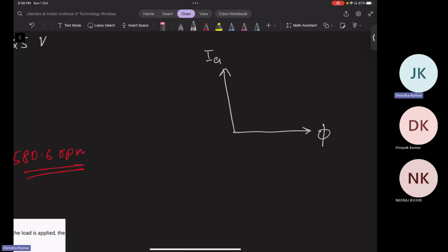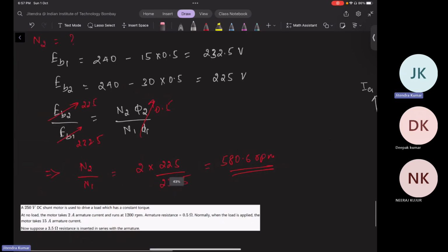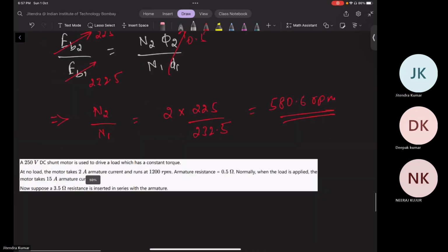If you ever want to use the DC machine in any kind of traction application where you want to control field separately and armature current separately, this is the best machine. And in all the advanced control of advanced machines, basically what they do is decouple the armature current and field flux so that they can control it very simply. That's the whole purpose of control of all the advanced machines.